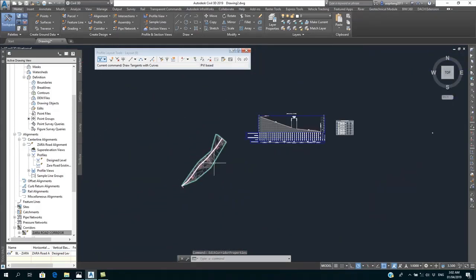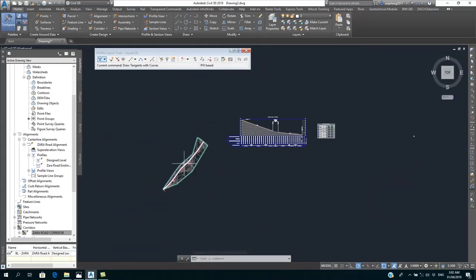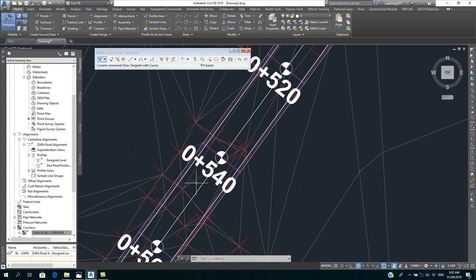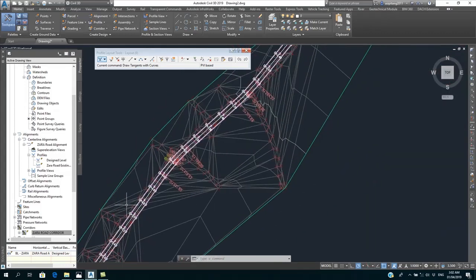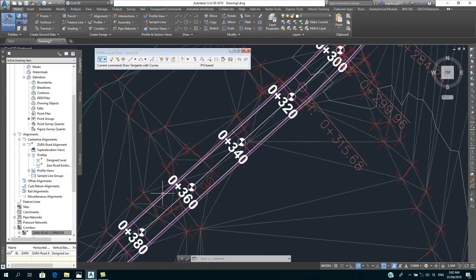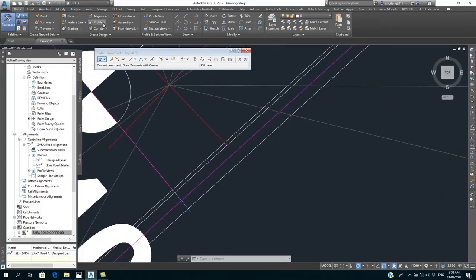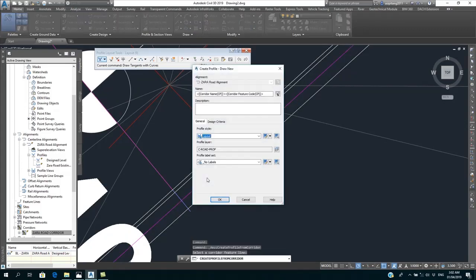Then the next thing you're going to have is to create what we call, we have created a surface, corridor surface now. So what we need to create now is, okay, I've created a lot of it. I can now create a profile for this invert level. What I do, I'll now click on profile, create profile from corridor. I'll now select the invert level lines and give it a name, maybe drainage invert levels.